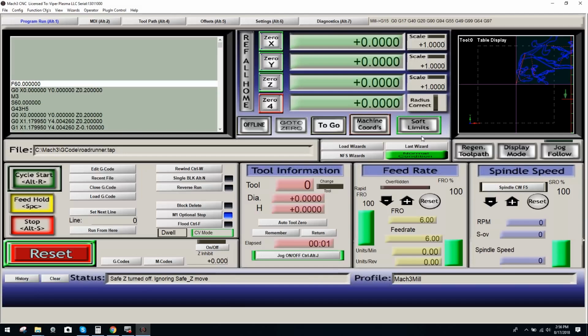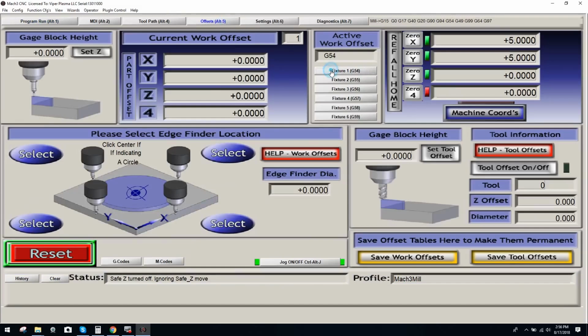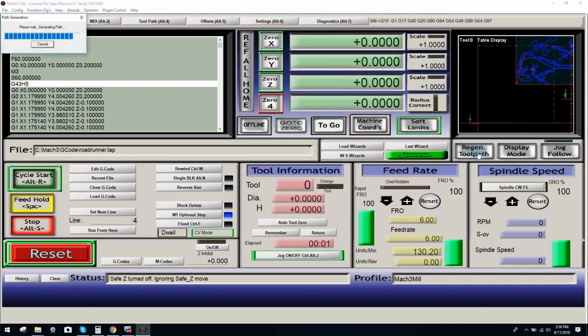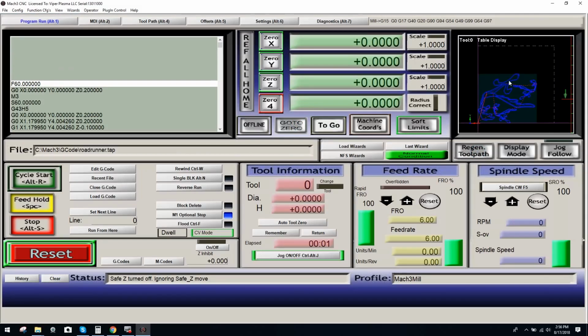If you look at the speed, if we go through this process, and even if I'm checking it here, you can see I'm in G55 right here. Let's say I was just loading this myself, and I said, nope, I'm exceeding there. I would have to machine at the bottom corner. All I would have to do is come over my offset, come back to G54, go to program, come over here to go to 0, so I can now regenerate the toolpath in the corner. Done, and there I go. I'm ready to go. So you can see how fast you can move back and forth. It's very, very fluid, and it saves you a lot of time and hassle. This way works extremely well.